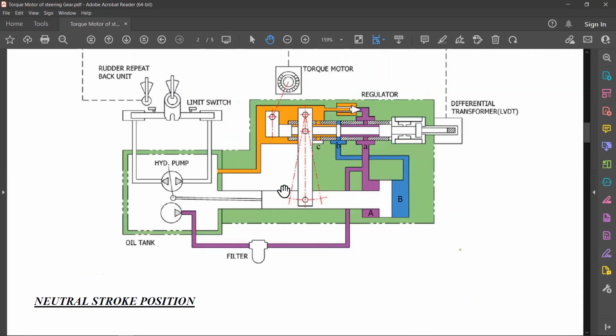this entire system works like this: there is oil which is coming up here from the main reservoir. This is the lead off line. It is going back to the reservoir. This is the auxiliary pump which is operating this entire servo piston. Okay, and as this pump operates, it will give the oil to either this side or this side, more or less.